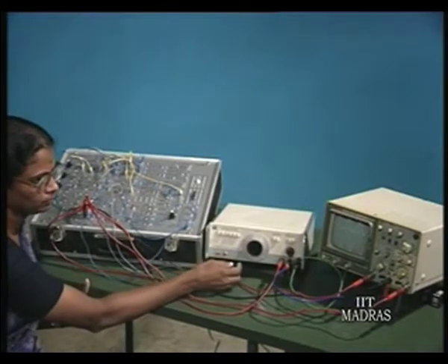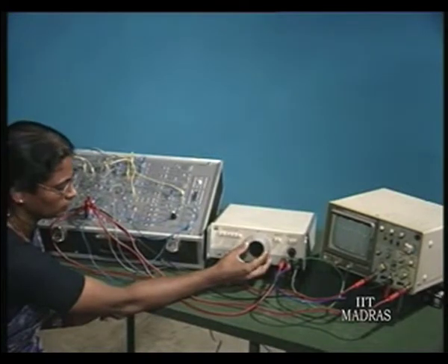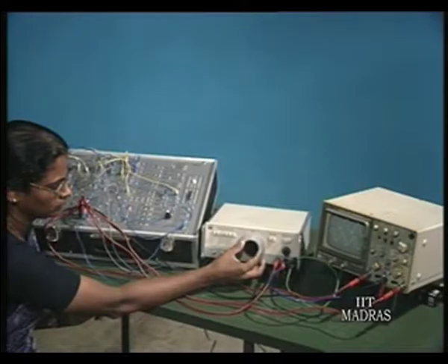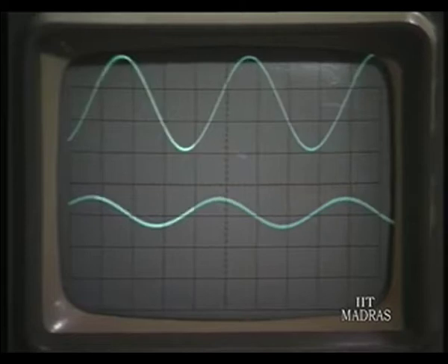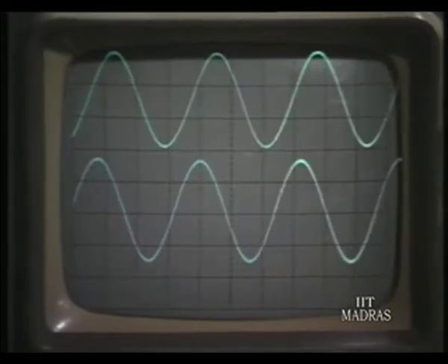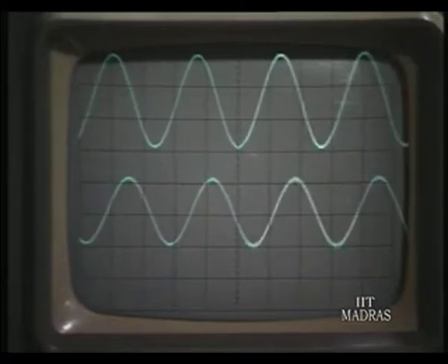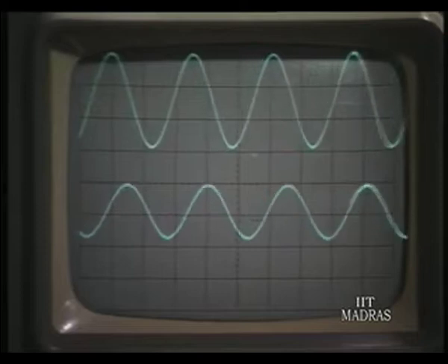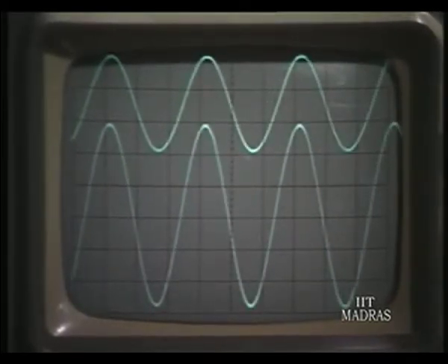Okay. So, you can see this as she varies that frequency, on either side of this it is decreasing. That is why, see, it is decreasing on one side, now you increase, yeah, it is peaking. Again she is changing in the same direction and it is decreasing on the other side also. Okay. So, that is why it is going to give maximum gain at center frequency.